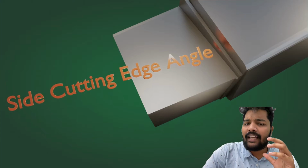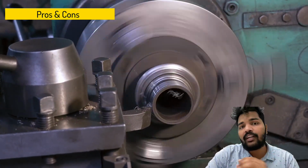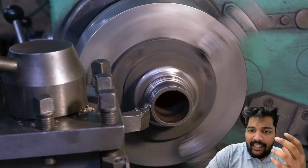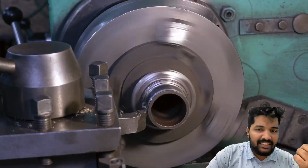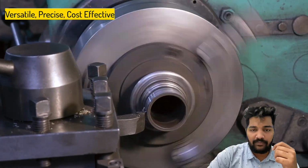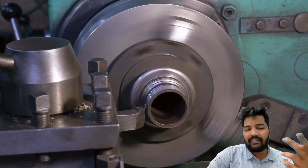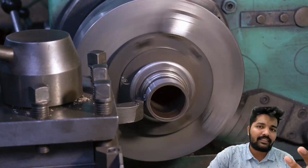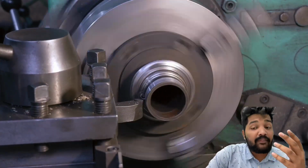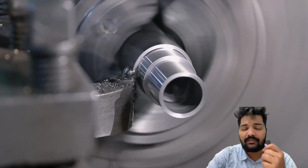Now that we understand the angles, let us talk about the advantages and disadvantages of this single point cutting tool. To begin with the advantages, the single point cutting tool is a versatile tool, precise and cost effective to manufacture. It works on materials like metal, wood, plastic very easily. But like the two sides of a coin, this tool also has its disadvantages. It may wear out faster, have a shorter life, and be a bit slower compared to other tools.